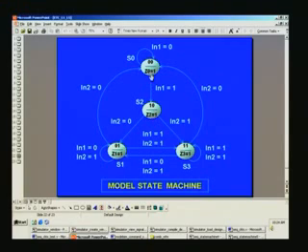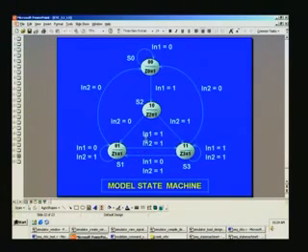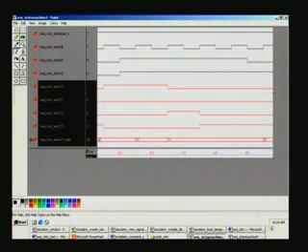From here it has to necessarily go through this state. So it has to go to S2 state here. That's what is happening here. In S2 state, in 1 both are 1 here. So where should we go? Both are 1, right? So it's going to S3 state. That's what is happening here, and it continues to remain in S3 state so long as the inputs are the same, and in fact it is the same right up to this, and then finally it goes to 0 1 here. So that is for the 0 1 transition.